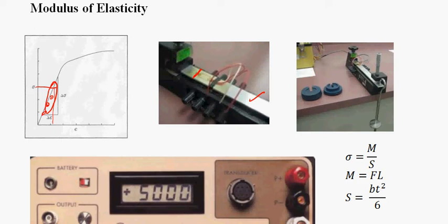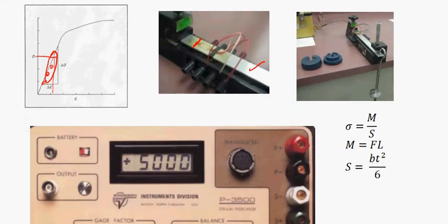Now we need to get the amount of stress in that same element, the amount of stress at that location on the beam. And the beam is in bending, so the way we're going to do that is incrementally put the loads to create a bending stress at that location, and we can calculate that amount of stress by the amount of moment and the section modulus.